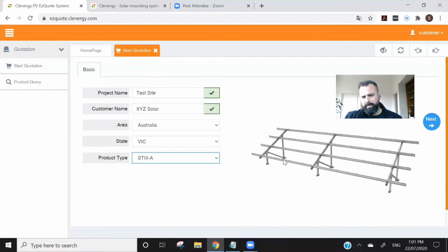Another reason is if you've got a particularly challenging soil, for example, very sandy soil, then this system can be used with ground screws, which provide a bit of a better hold in porous soil condition sites. Also, we're looking at a project at the moment which is a landfill site where you can't penetrate the soil more than 400, 500 mil or something like that. In those cases, this system can be attached to concrete pads, so you can have concrete strip footing, concrete pylons, really whatever your preference is.